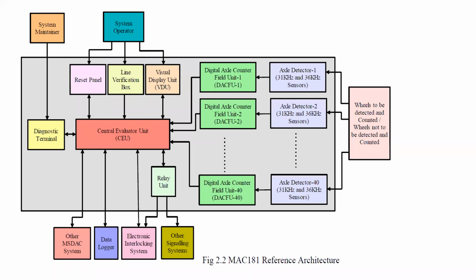Mr. Hashmi has asked how the digitizer works. Yes, it is a digitizer. Digitizer means it converts the analog signals that are processed and available in the transmitter and receiver, that is the received signal, which is an analog signal, into digital counts. It has to say count 1, count 2, count 3, instead of saying that the voltage has become 5.5 volts, 6.5 or 0 volts. That is the analog to digital conversion.